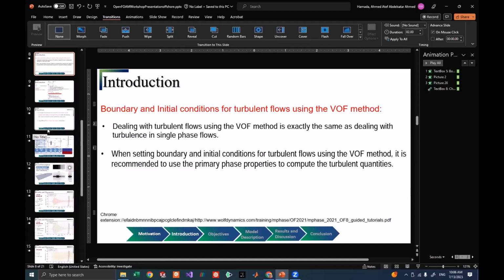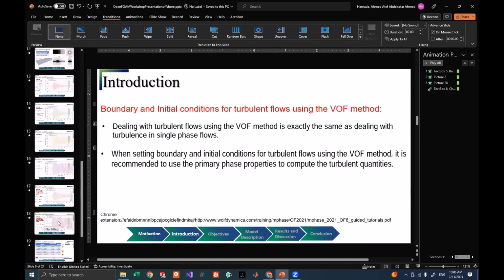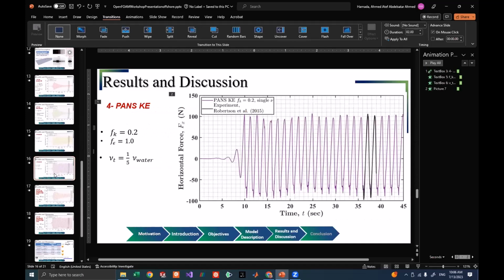Okay, so I am assuming at the end of the simulation, throughout the domain, FK is 0.2. It does not change according to the wall cell size, because PANS is supposed to be a bit grid dependent, right? Yes. And my second question is, when you start PANS with FK 0.2 or 0.7, there have been some studies by Dr. Girimaji himself that they start with running a full case simulation and they use that field data to start the PANS calculation. Is that the case here, or has this been started with no input data from any other run?